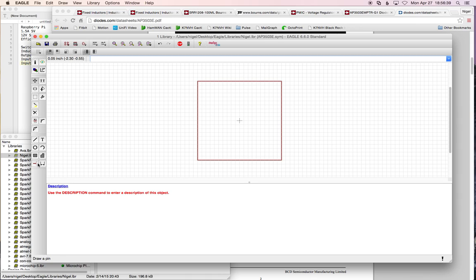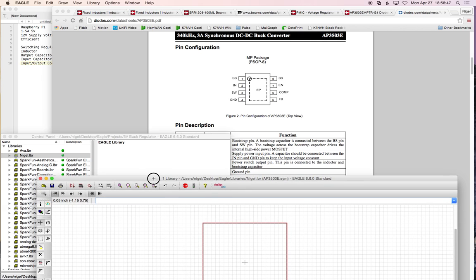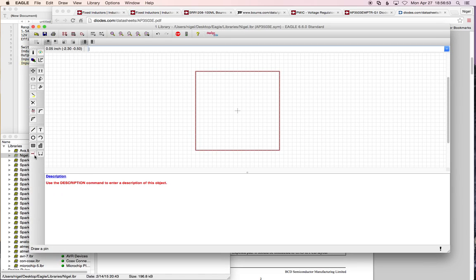And then we start looking at, okay, let's put some pins on it. In this case, we've got 8 pins plus the ground pad on the bottom. They call it the exposed pad, EP, there in the box on the drawing. And so we'll take some pins and let's stick them on here. 1, 2, 3, 4, and then I'll put this one a little bit farther off, 5, and then 6, 7, 8, 9. So these will be pins 1 through 8 here, and then we'll leave this as our exposed pad. So I'm done adding pins, so we can stop there.